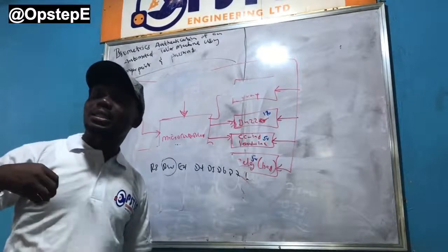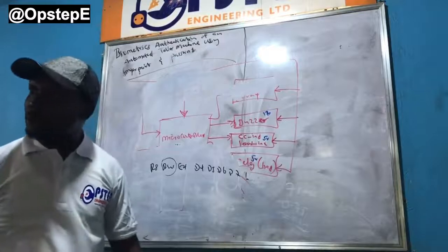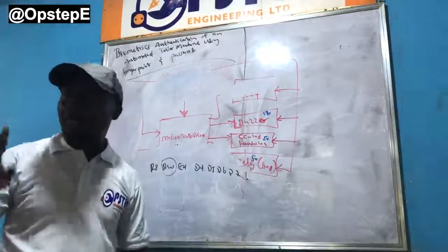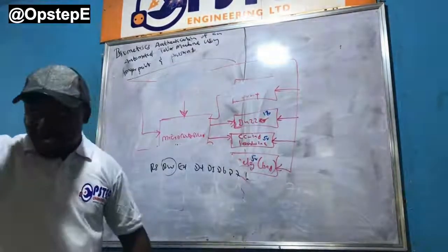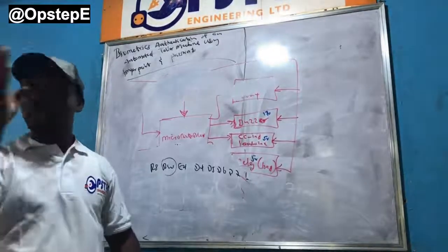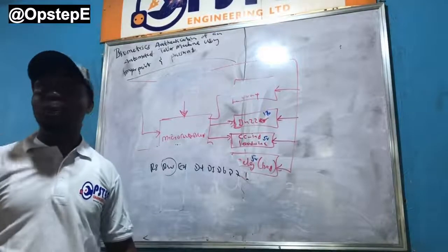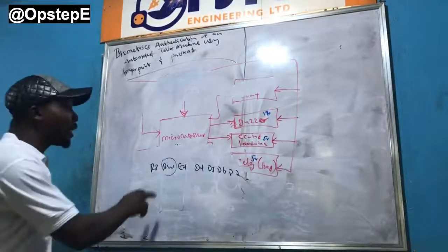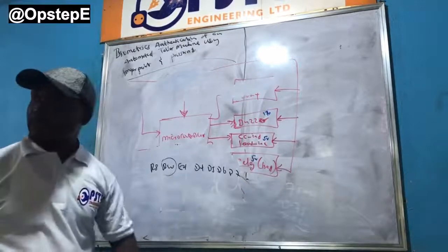What it means is that for you to see a positive output on it, you need to put a pull-up on it. That's why in most of my designs, I only use that pin as input. If I need several inputs on the controller, I start from that pin, that T0CKI. Then I can take the other inputs from anywhere. Because it will not serve the purpose of an output pin unless you put a pull-up, which is an extra component for me on the board. But now that it's been connected to an LCD, you have to put a 10K resistor on that pin.